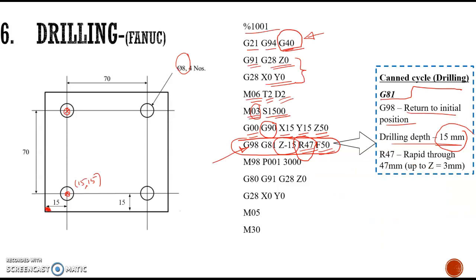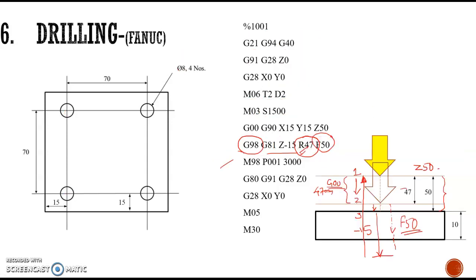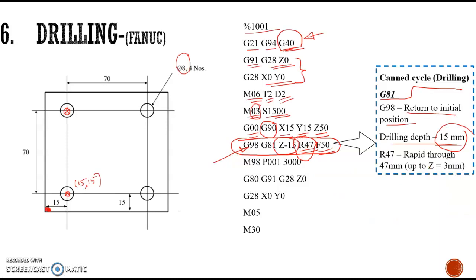After giving the canned cycle for drilling, the next block is the subprogram, and in the subprogram we are writing the position of all the holes.